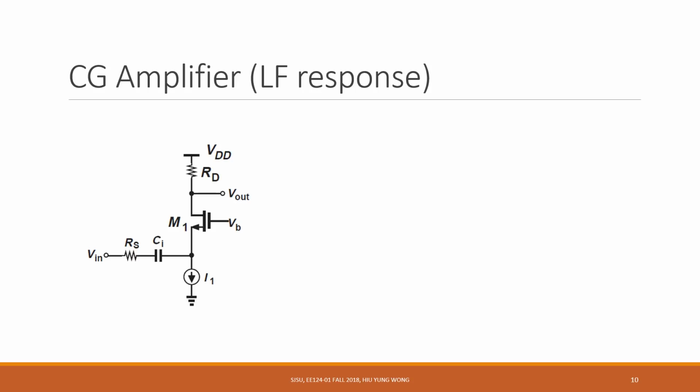Now we are going to another part called the common gate amplifier. This is something very special. For the common gate amplifier, you are tempted to use the same method we have learned, but sometimes for some circuits you cannot use those methods. For example, here, how do you find the input pole? The capacitor is not connected to ground, right?